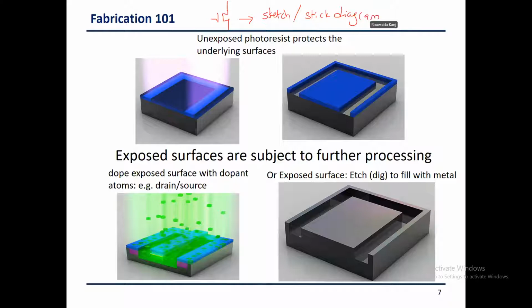And this stick diagram is going to tell me, well, on the chip, if this is your chip and you want to draw this small gate in it, I expect that this gate will have VDD here, ground here, the NMOS transistor, the PMOS transistors here, the NMOS transistors here, and this is the output.